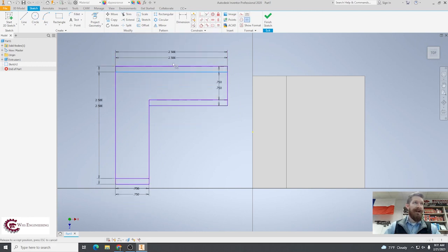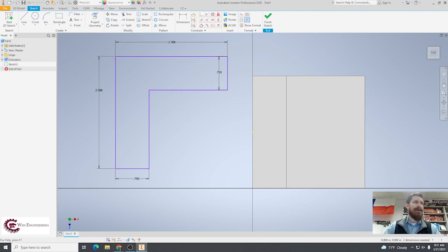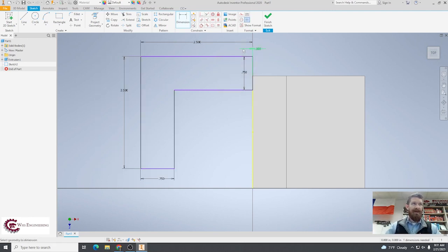So one way to do that is to say I'm going to dimension from here to here. I want these things to touch. So when 2 things are touching, the space between them becomes 0. You can dimension something to 0. That's one way to do it, right?